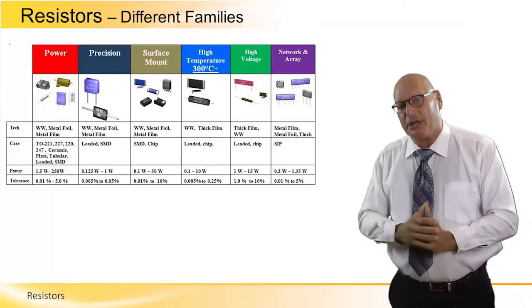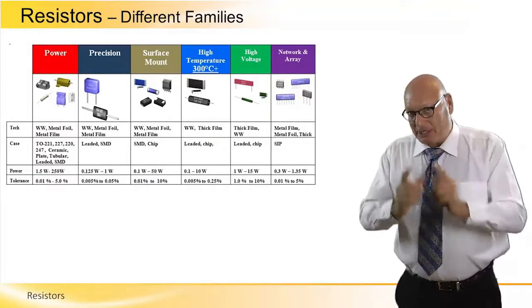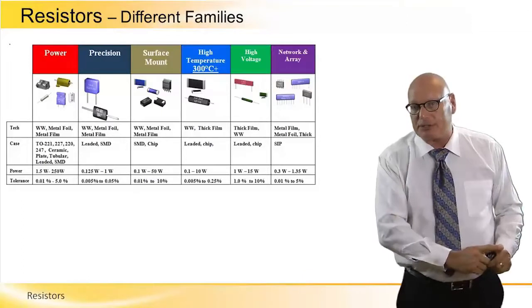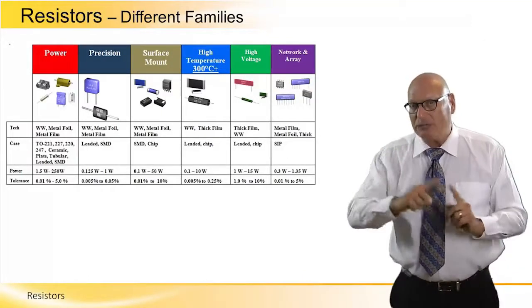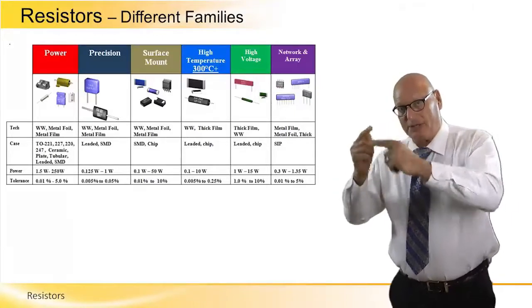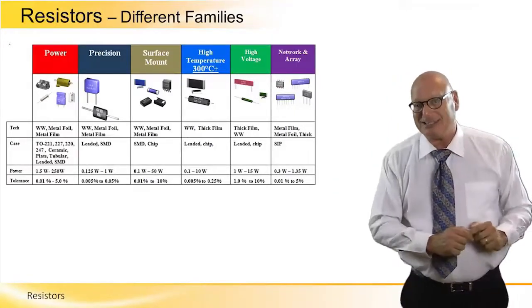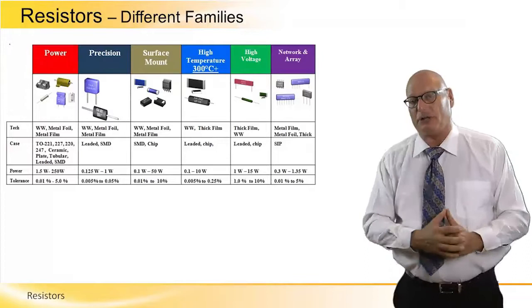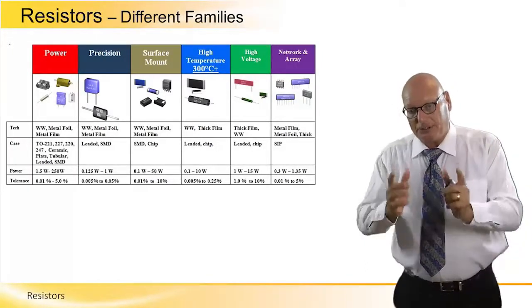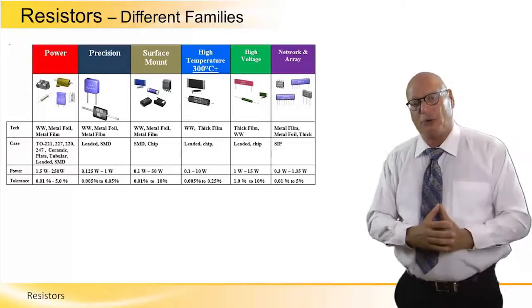This is very precise. Now, please keep in mind, powered resistors and high precision resistors normally don't go together, because as the temperature rises, it changes the resistance material, the resistivity of the material itself. But yet, the tolerance can go down to 0.1%.